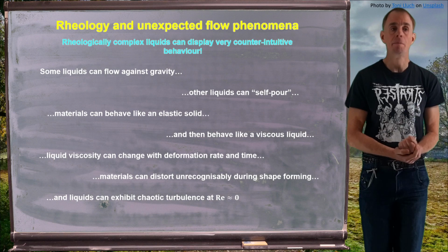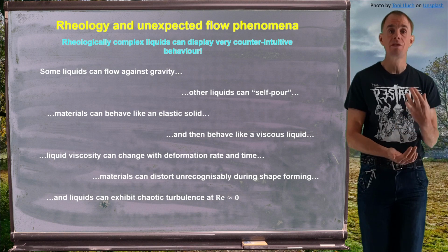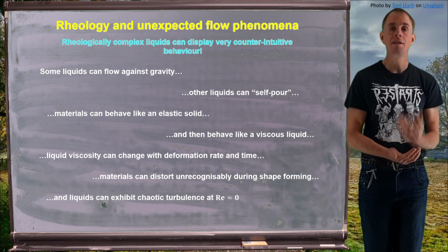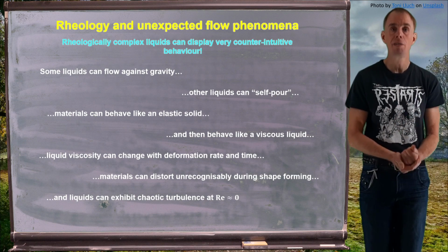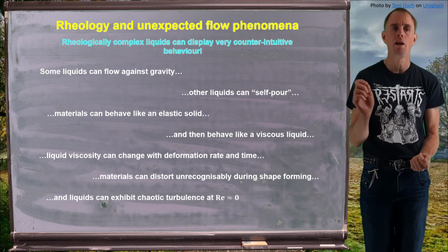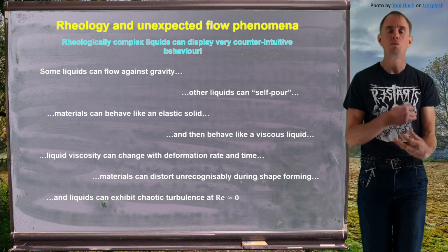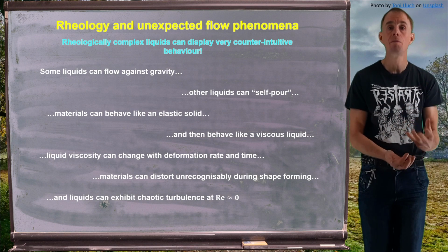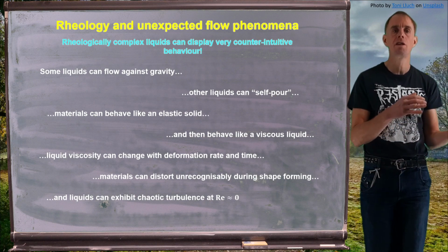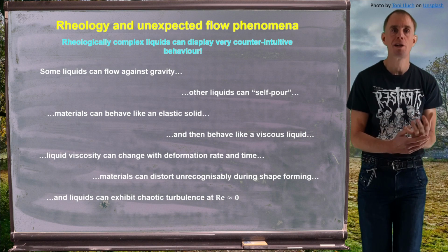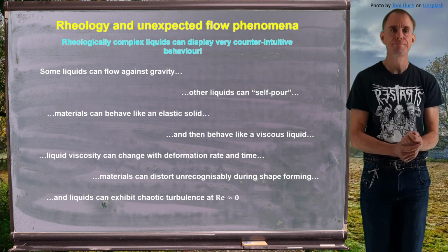Back to the paint problem. Liquid viscosities can change with deformation rate and time. So there's sometimes a need to have low viscosities at high deformation rates. Think about painting a wall. You want the paint to go on nice and easily, you want it to flow. But you want very, very high viscosities at low deformation rates, or at long times after it's been applied to a wall. And so you've got these interesting behaviours where material properties change as a function of deformation rate and as a function of time.